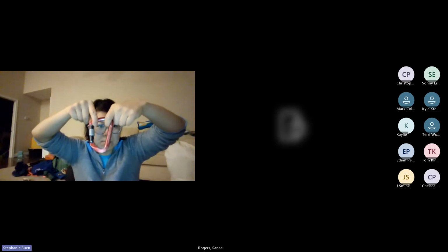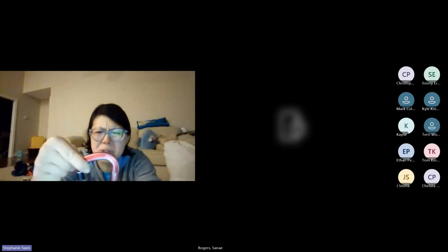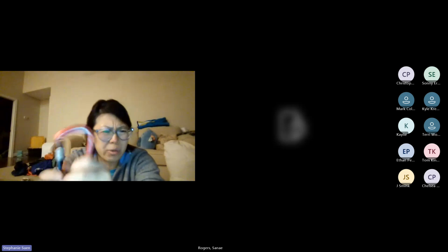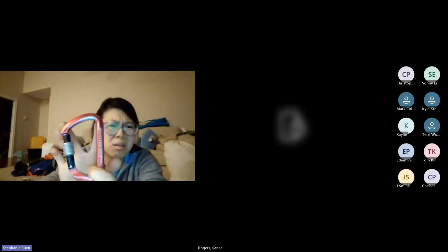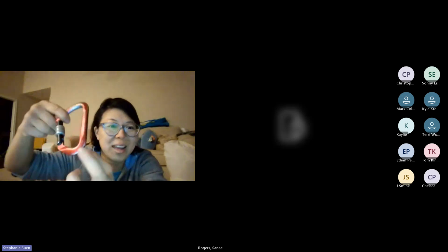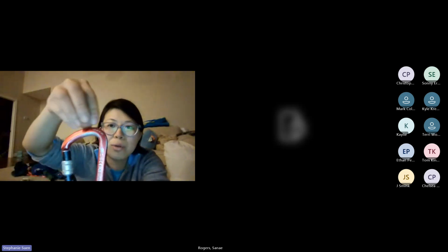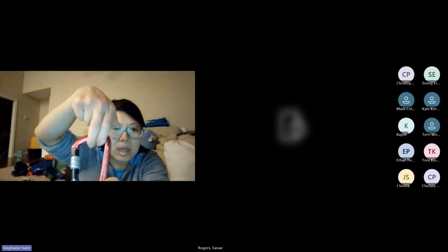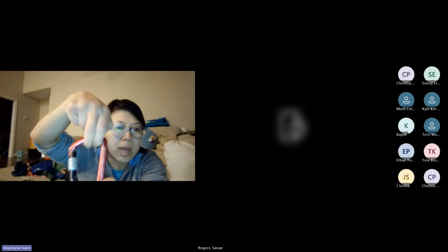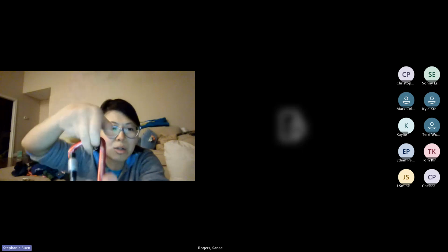So if you've ever seen, there's this failure mode, there's photos where the carabiner nose, like this nose here, has bent outwards. That's sort of where that comes from. And if you read the manufacturer booklets, they'll talk about that as well, where they say don't do the tri-load. So if you do have that basket hitch, you want to land both ends of that basket kind of in here if you can, right? Not too hard to do.